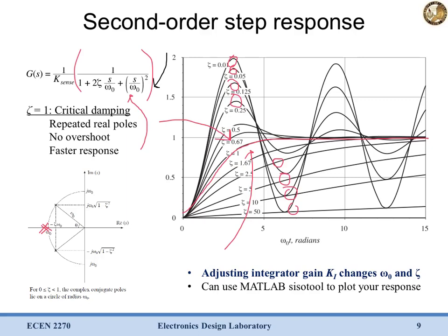And that's what we'd like to solve for. We'd like to adjust our integral gain k sub I such that we have a critically damped system. Remember, adjusting k sub I is going to vary zeta and is going to allow us to change how our system reacts. We want to solve for k sub I such that we have a double root. Now we can do this by hand, or we can do it using some program, Mathematica or something, but that's fairly difficult, and for larger systems it's just going to become unwieldy. It's not going to be an easy thing to do.